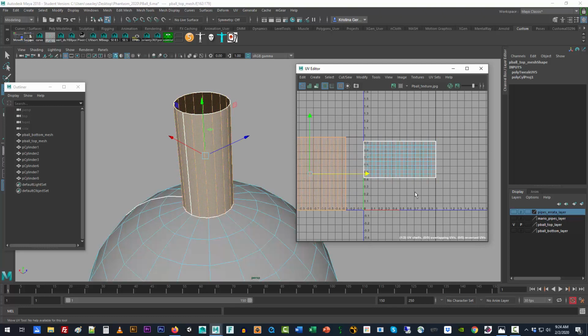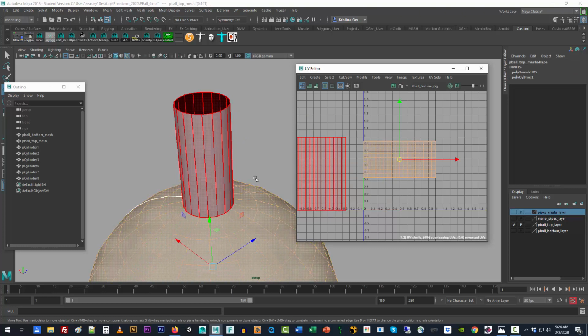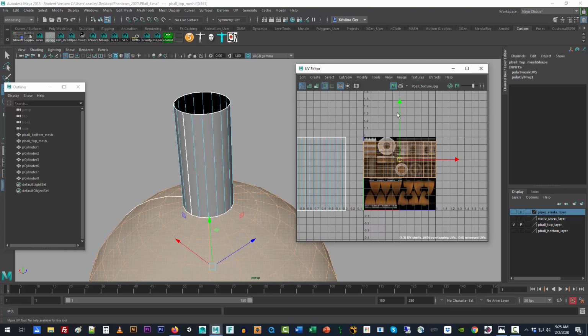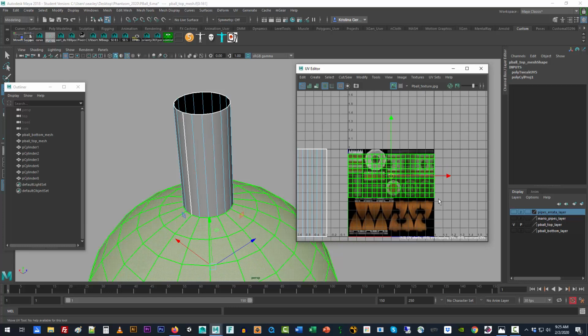Just press W. You can move it off to the side. So in this case, because we can see the picture, we want to take this and cut it up in the same way that we did the original ones. We're going to use the same method as for the bottom of the Phantasm Ball, which was a similar half dome. So we're going to select the appropriate strips and then unfold, making sure that we have one untouched line of polygons for it to be anchored.